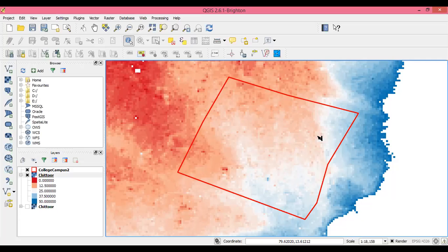So if you think about it, it's a simple, straightforward procedure, but you just have to go through these different steps. Depending on the area that you're looking at, you may get different types of land use. You'll have to estimate what the runoff coefficients for those will be. Depending on the topography, you will have to find out the slope and the length of travel for your chosen area. From that, you will estimate the peak rainfall intensity and the time of concentration, and thereby you will find out the peak runoff rate for your campus. Is that okay?